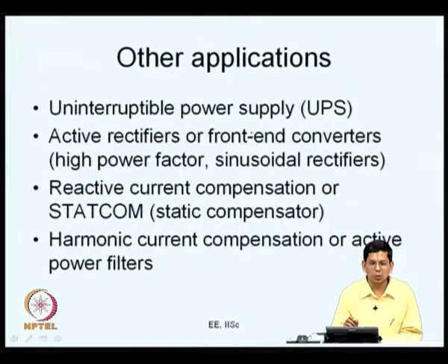You only control the voltage, and again, as I said, the battery requires to be charged. So, whenever the mains voltage is available, the battery gets charged, and whenever the mains quality is not up to the mark, for example if the voltage is a little higher or lower than what is expected, once again the load is not directly fed from the mains, but is fed through the inverter. You rectify and then you invert and you feed the load. So, that is what we saw about an uninterruptible power supply.